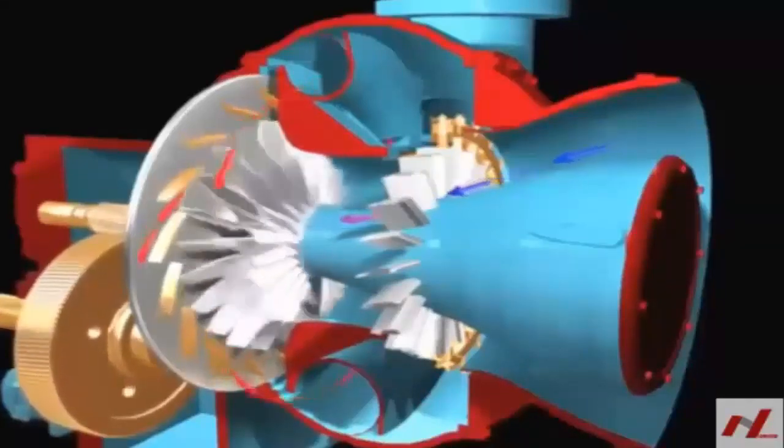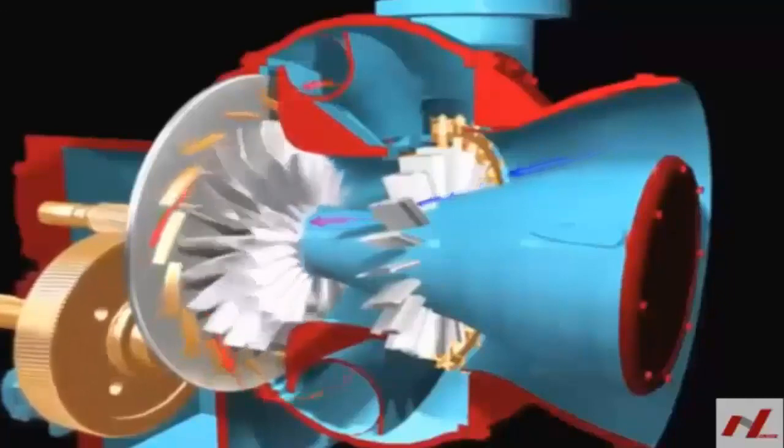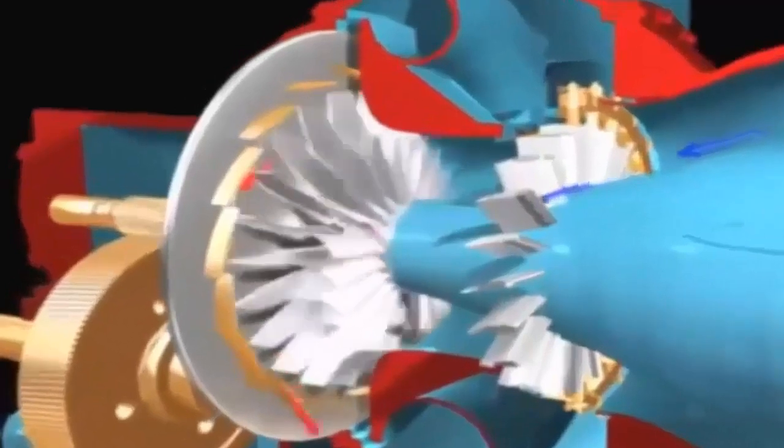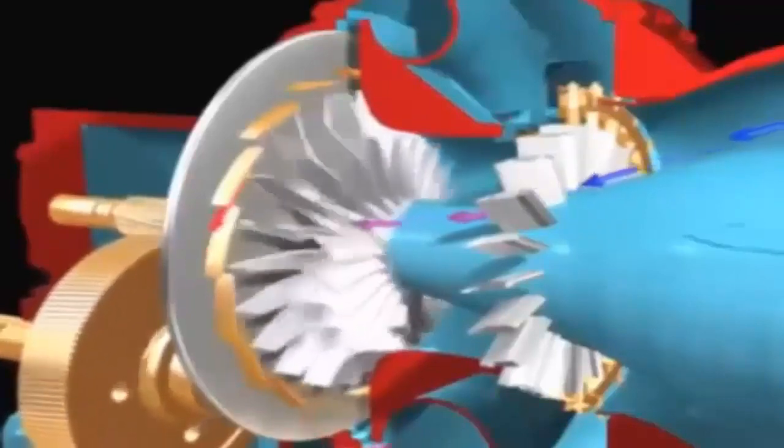Another way to regulate it is also varying the speed. Here we are just changing the passage area. By changing the speed we are also going to change the amount of refrigerant that is being supplied, but also since the compression is generated by speed, it is easy to understand that if the speed is lowering, the refrigerant pressure will also be affected. The only effect is the amount of refrigerant. Then the RPM of the centrifugal compressor is being varied.